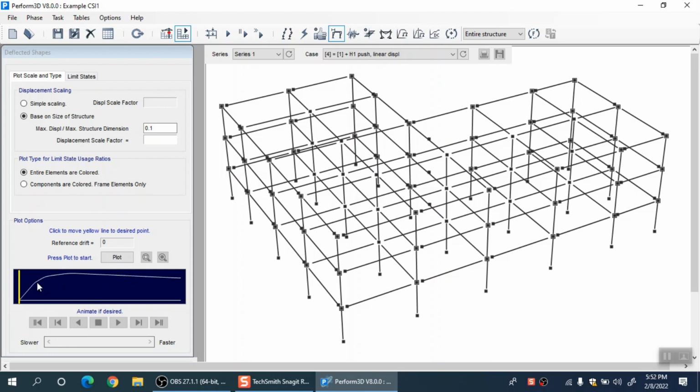For example, we can see what will happen to our structure at what level of loading, because we are not applying a fixed loading in the static lateral direction, we are applying a monotonically increasing loading. So loading starts from a very low number and it increases until the structure has collapsed completely. So the whole life of your structure, the whole spectrum of the performances is already with you, because you keep on pushing it.